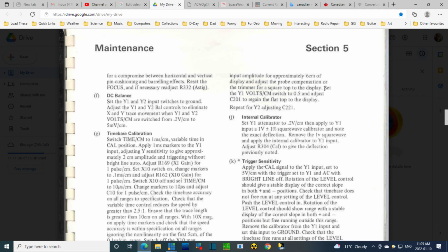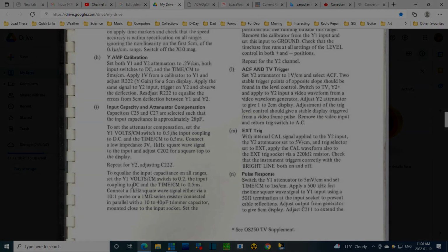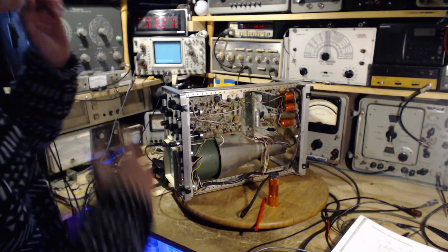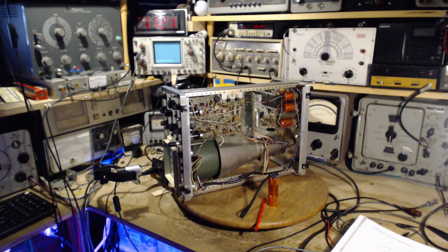So you're matching one to the other. You're either going to match the scope to the probe or the probe to the scope. Now I've got multiple probes here, which is obviously a problem. Set my, well, what am I going to do? I'm going to stop and ponder this a little bit before I do anything. Okay, so what I've chosen to do is use the square wave that's provided by this signal generator. I think I'm probably quite safe trusting it. So we'll take a look at the square wave on this scope here and the adjustment.